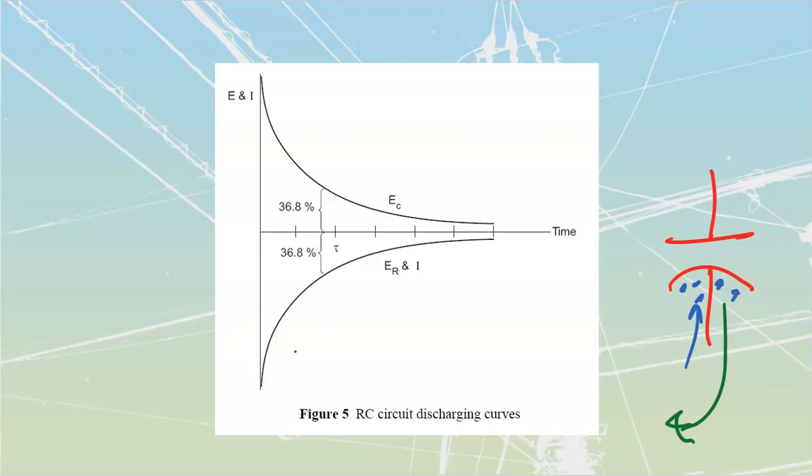Underneath the drawing that they show for that one, they do talk about capacitors inside of the Canadian Electrical Code. We covered that. We looked at how we need to have these things discharged in under 1 minute if we're going to be under 600 volts. That's going to include pieces of equipment like variable frequency drives and stuff like that. Generally speaking, I still don't touch them for about 5 minutes.